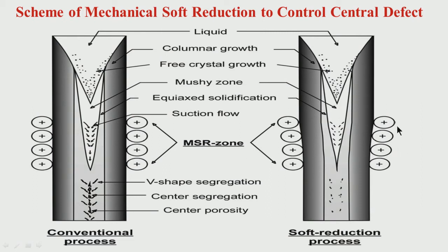Look at here what is happening. This was the original thickness dimension. You are putting some additional pressure in the final solidification zone. So, what is happening? The thickness is slowly coming down, not in one step, not at only one location, but slowly. That means there is a gradient in how the thickness is coming down. You are putting pressure in the rolls, you are decreasing the distance between the rolls in these areas.